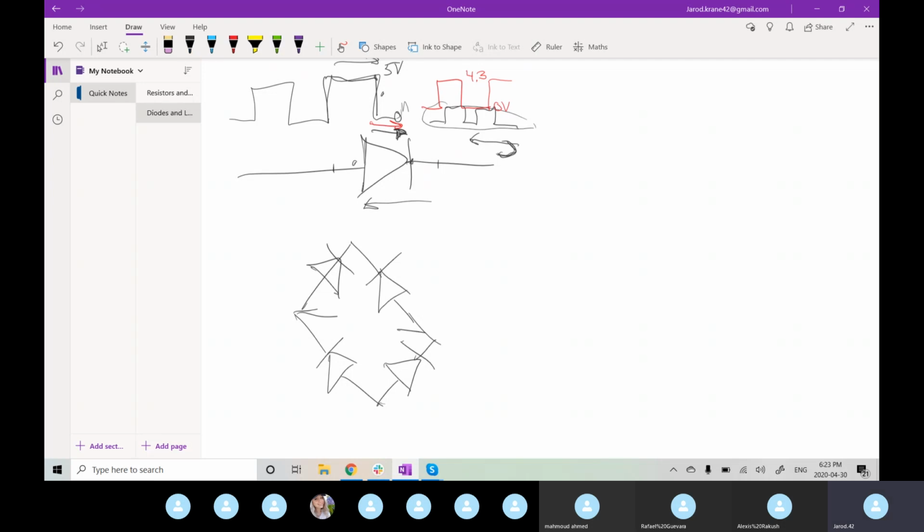No. Why can't I remember what a rectifier is? KBL out. Do I have this drawn? Yep. Like the AC goes on the top and bottom, and then you take the DC from the middle. But your top right diode should point the other way, and your bottom left should point the other way as well. That's what I thought. Yeah, it's like a little path.